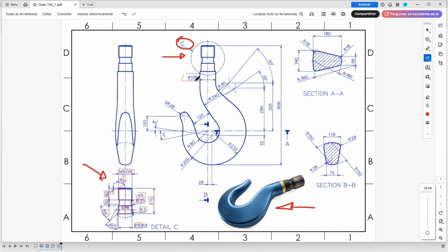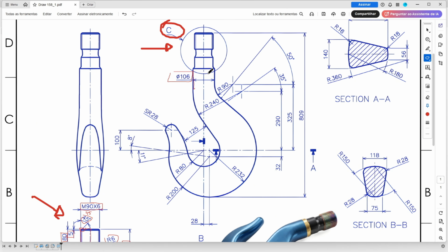And now we will create the guide rails here. This sketch will be in the front plane. And the first thing that we'll make, we will take some reference. And the reference of this body here, we'll make a reference here, this line. And we need to make this point for reference, okay? And this point is in the center, so it will be horizontal vertical with the midpoint. And the distance between this point here and this point will be 809